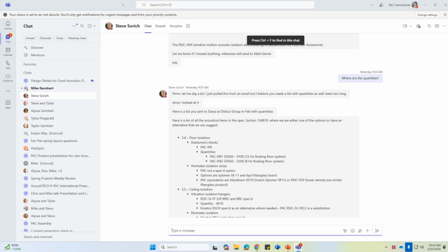It was interesting. I was just looking because we're doing these shear wall tests, and the lab was asking me what screw pattern to use to attach the shear panels to the studs. So I was going through some Woodworks documents for guidance on screw spacing, these kinds of things, because there's a whole bunch of variation in that, and I wanted to make sure that what we were actually testing was applicable to the real world.